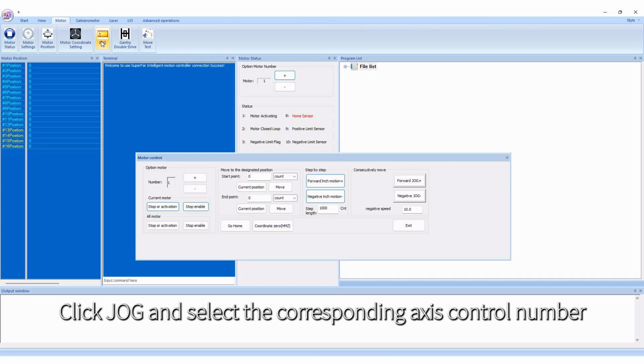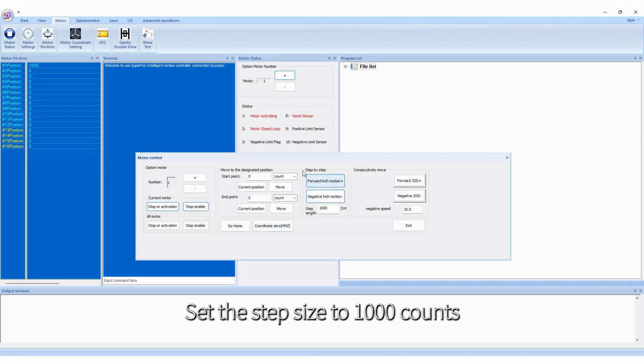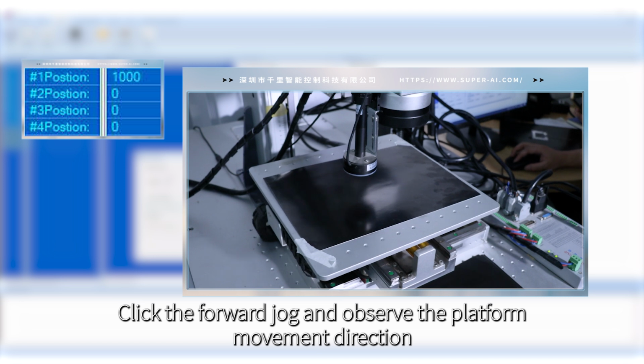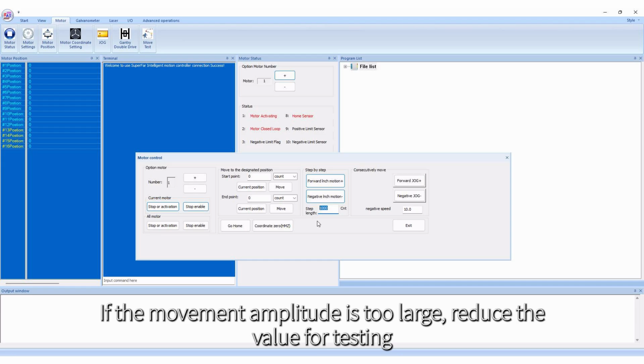Click Jog and select the corresponding axis control number. Click Stop or Activate Enable to activate the motor enable. Set the step size to 1000 counts. Click the forward jog and observe the platform movement direction, whether it matches the encoder feedback value. If the movement amplitude is too large, reduce the value for testing.